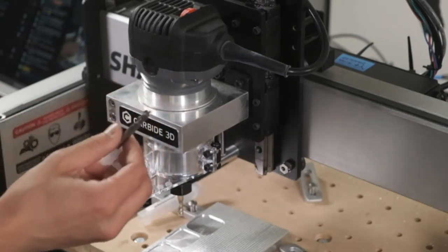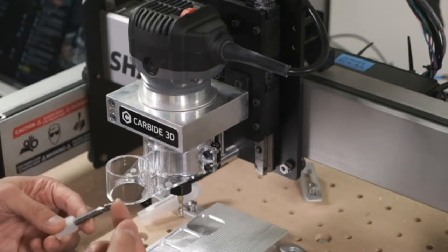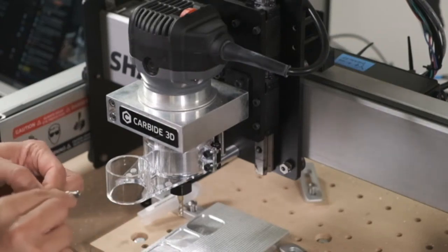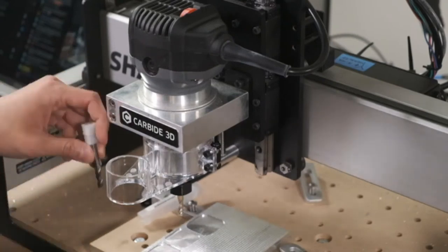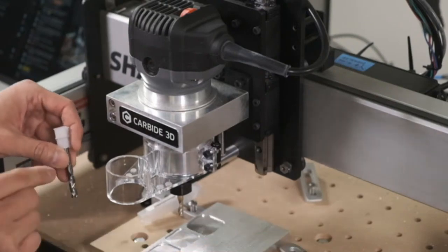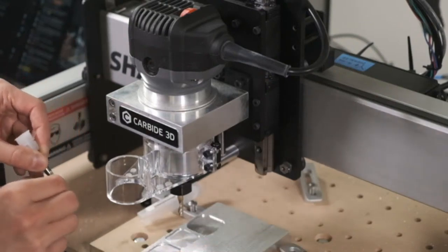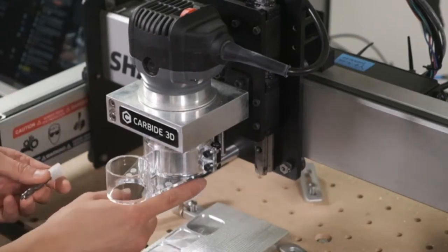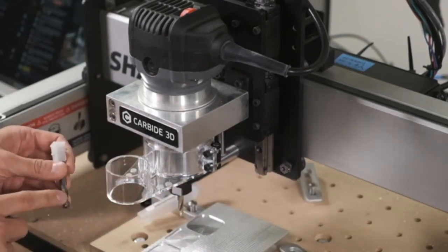The other thing about this is because it's 3 flutes, there's 3 separate cutting edges. Each of the valleys in there, the flutes, is a little smaller. So if you're machining a deep pocket, chips might not get out fast enough. They'll start clogging this, they'll start fusing, they'll start melting, and eventually your cut will fail. So a single flute gives you more margin for error in terms of clearing out the flutes.